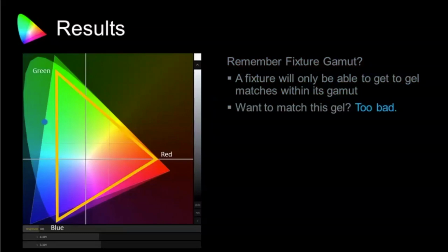What's really nice about an incandescent source is it's outputting light at everything in the visible spectrum that the human eye can perceive. And so that whole horseshoe space of the CIE color spectrum, gel can get to, because gel has the ability to filter or pass wavelengths that get it anywhere in that spectrum. Additive color fixtures in particular may not have the ability to provide a full source. And with subtractive color systems with arc sources, or white light LED sources, you also have to consider the gamut, because the white source may not be full spectrum in the same way that an incandescent or daylight is.